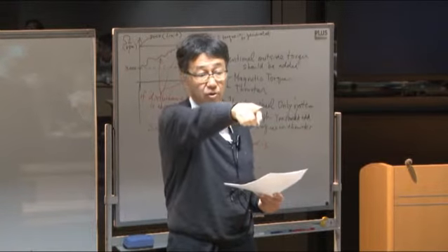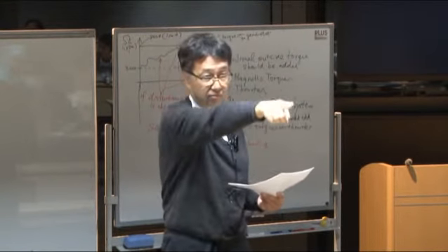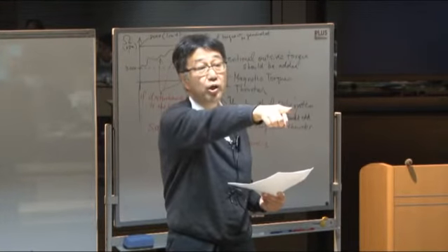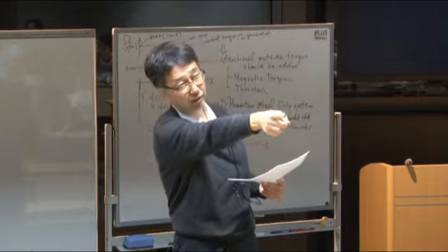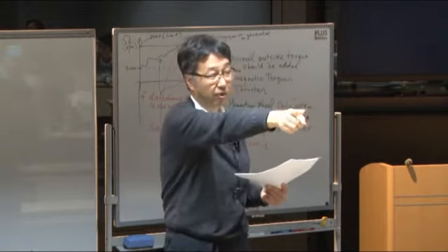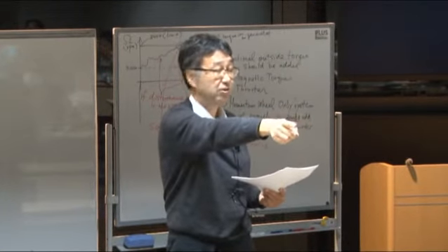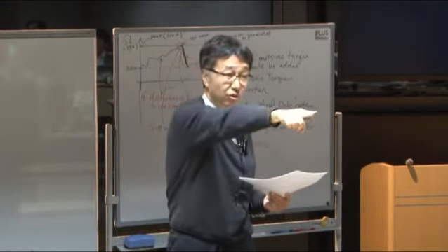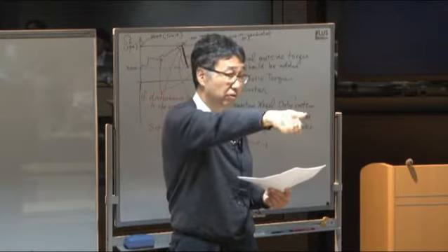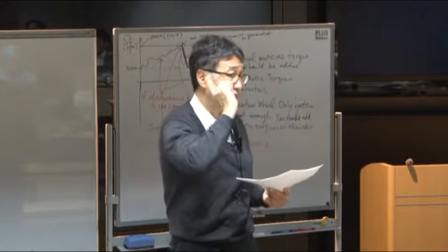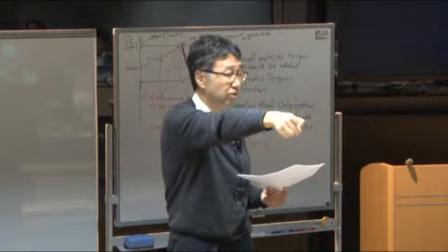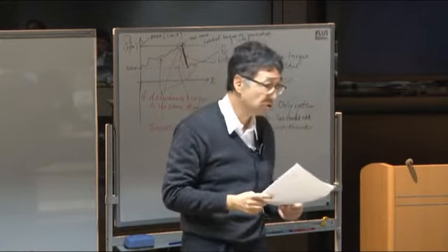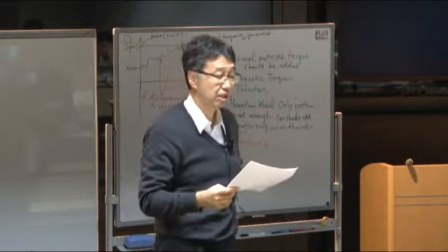And if we have a roll error, then the antenna moves like this. Okay? And if we have a yaw error, then the antenna moves like this. So maybe you understand. So your axis does not strictly control, because it's only the rotation. Even if the satellite rotates around your axis, maybe the antenna or camera direction does not change very much. So in that sense, the yaw axis usually has a less stringent requirement.